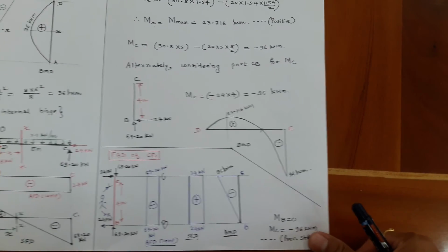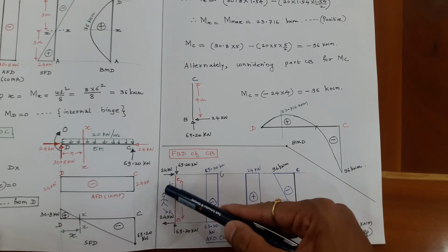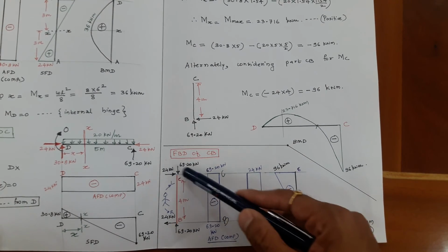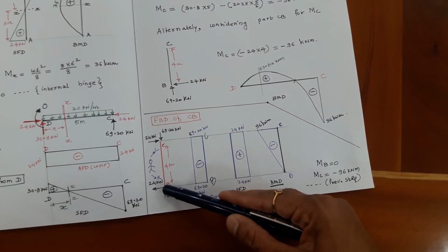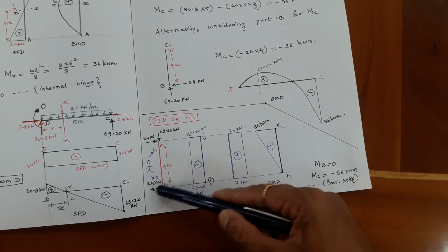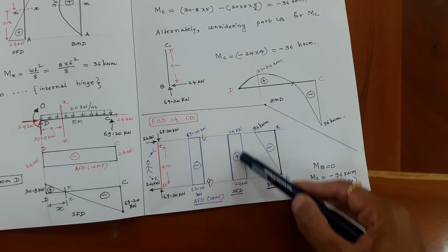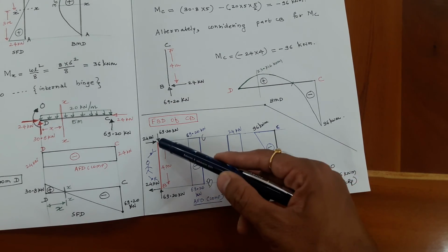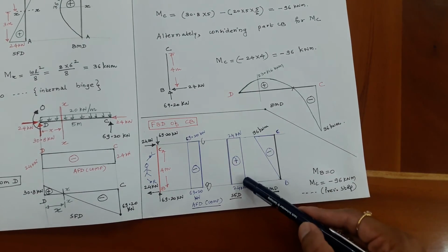Now coming to the shear force diagram, it is always better to imagine that you are standing inside, and this is your left, this is your right. Because of 24, your left is going up, so left up is positive 24. Because of this 24, right is going down, right down is also positive, so that is also outside. I have joined it with a straight line, plus. Alternatively, you can say that between C and B there is no load, so shear force will remain the same.